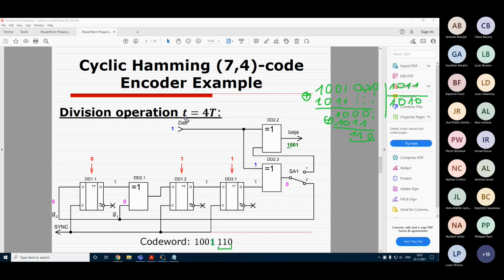And as you can see, after 4 intervals, we have this 1, 1, 0. Please be aware that it's in mirror, because here we have serial data transmission, meaning that we send one symbol during one interval, and accordingly this will go out first, this will go out second, and this will go out last. And this will form the correct sequence of 1, 1, 0. So for that reason, this needs to be in mirror, and you need to consider that.